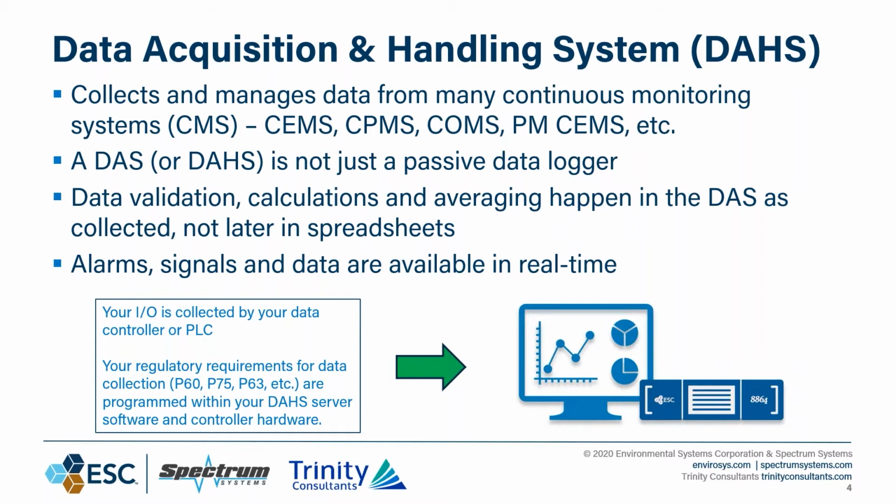Your DAS is not just the logger, it's not just the PLC, it's not the data controller, it's not just the black box. Your data validation, your equations, your averaging, whatever that looks like, they happen in the DAS as data is collected in real time, not later in spreadsheets. And your alarms, your signals, your data, your IO are available on a real-time basis as part of your system.